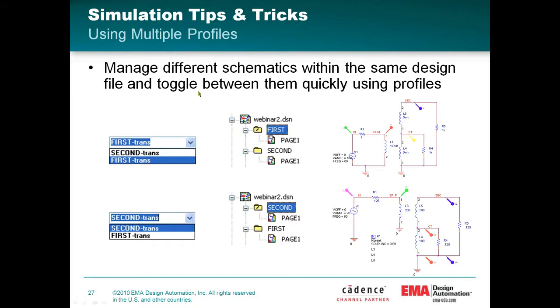The simulation profiles are kept separate because they're assigned to each folder name for each of the schematics. So for instance, to get one to have dominance over the other, in other words, if you want to run this first schematic, you would make that the root for the PSpice simulator, and then it would run everything corresponding to that particular simulation profile. Or you could just select that simulation profile and it automatically makes that particular design the root design for the simulation.